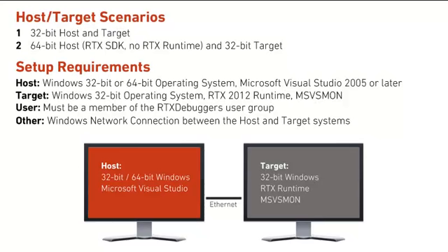In order to debug RTSS applications, the user must be a member of the RTX Debugger's user group. Note that the RTX runtime is not yet supported on 64-bit systems. Only full versions of RTX can be used in this configuration. Evaluation versions are not supported.